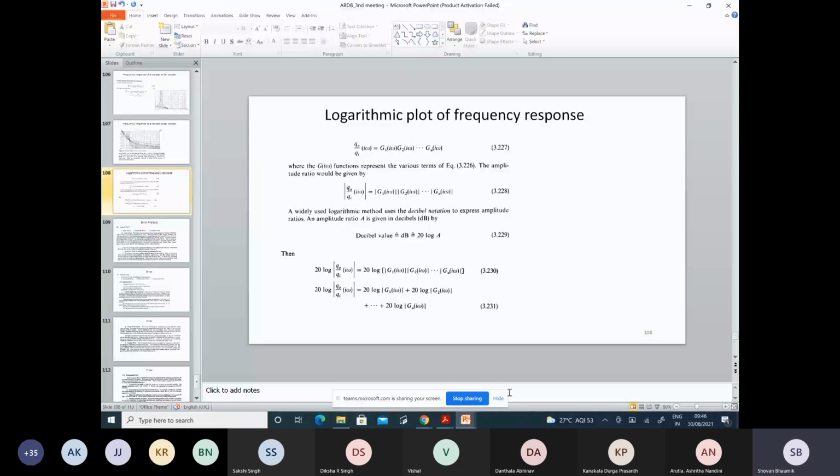What we generally do is that we know at what frequency range we need to operate, what the input will be, and what the lowest and highest frequency of the input will be. Generally we know it before operation. So we plot the Bode plot in this frequency range and see the gain and phase plot, and from such gain and phase plots we can calculate the transfer function accurately, at least for that frequency range. That frequency range is most important.